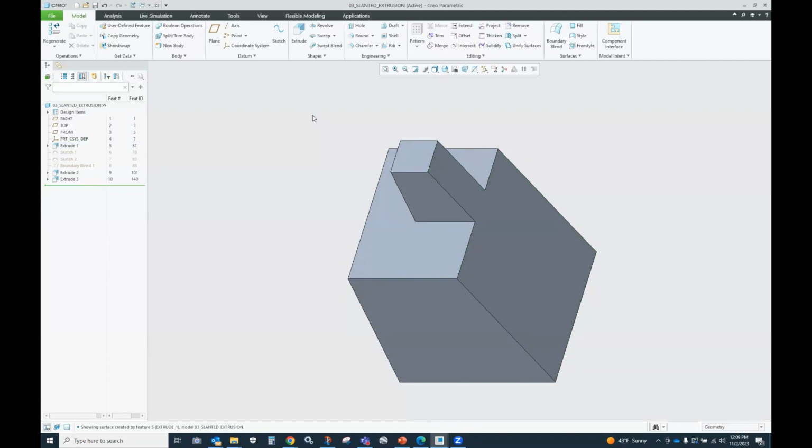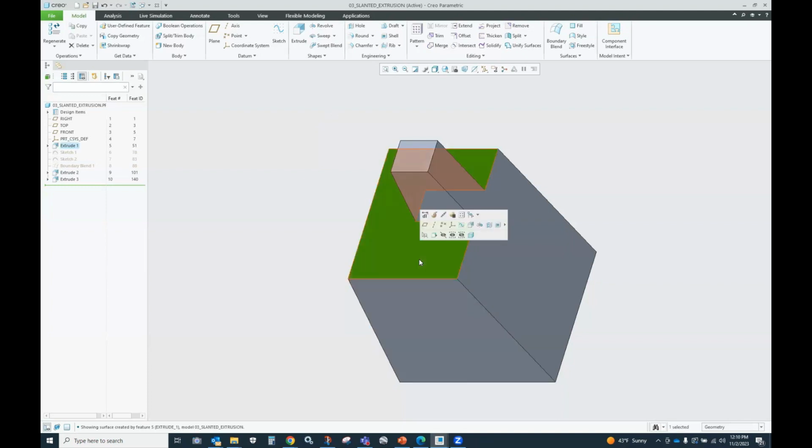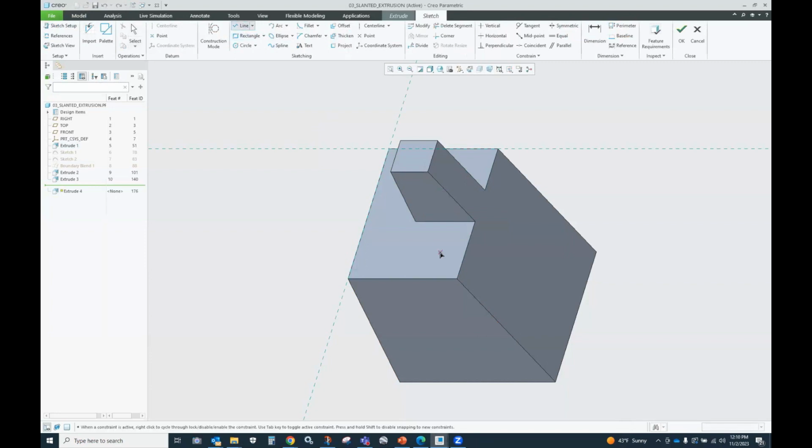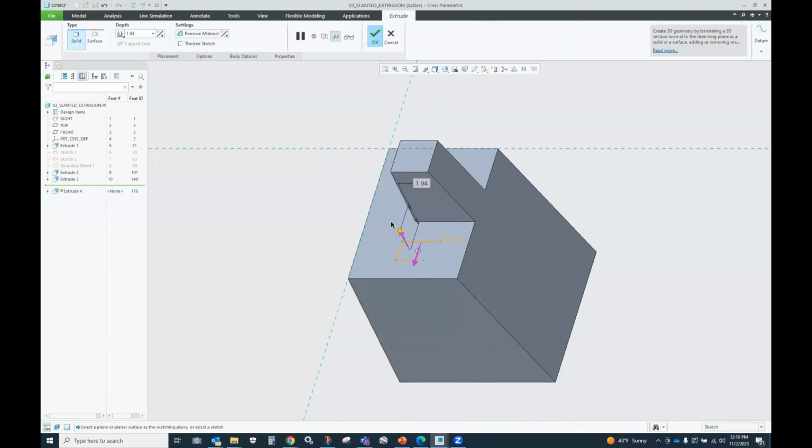So I'm going to kind of backtrack here of what I did wrong, just so everybody understands, and then leave the sketch open is the right answer here. So understanding how Creo uses open cross sections versus closed cross sections is important, because you can get more bang for your buck here if you know how Creo uses these open cross sections. Typically, when I create an extrusion with an open cross section, right, Creo wants to tell me that it can only make a surface out of it, right? It can't create that. It wants to create a surface or a thin solid. Those are my choices.